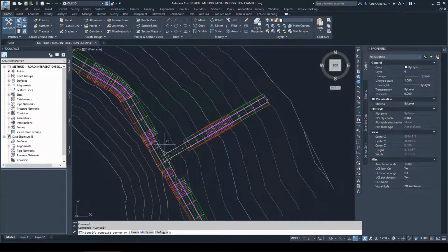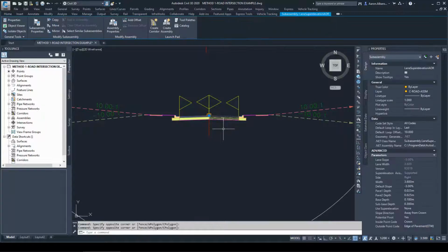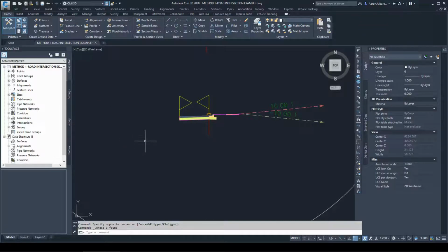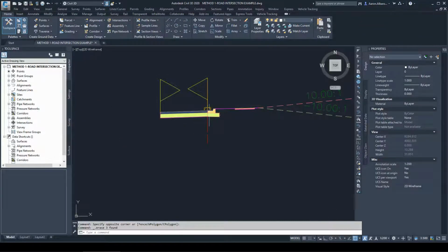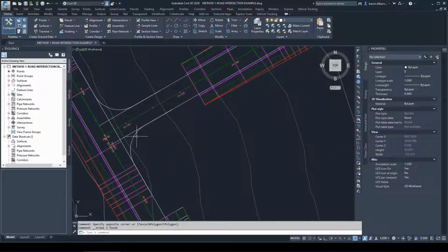So let's create that cross section as we agreed. The lane to the left hand side, so I should have a lane on the left hand side. I shouldn't have a lane on the right hand side. I'll delete that. And I shouldn't have those on the right hand side, only one lane on the left hand side. So this red line represents you walking on the edge of that road. You should see on that road the curb, sidewalk and daylight on your right, and you should see the lane on your left if you are walking again along this line here. If you're walking that, because that's what we created, clockwise movement.